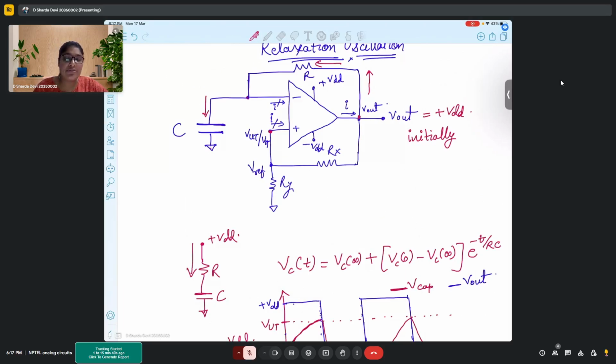You can keep a few capacitors in mind from the safety perspective, but the major concern here is the capacitance values, which are important to us, because based on capacitor and resistance values only we will get the charging and discharging time constants, and based on those we will get our wave's time period.